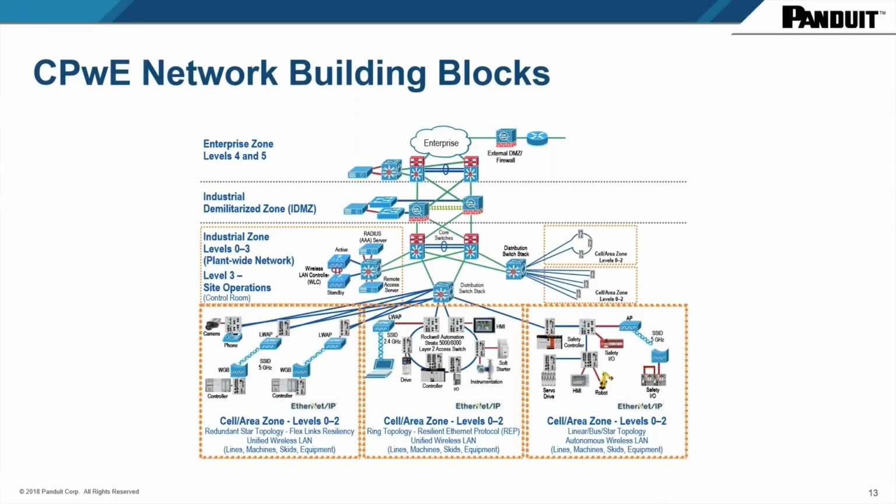As you go up in the architecture, you encounter what we call a DMZ space, and this is the demilitarized zone. This is where we find firewalls and so forth to separate the networks of an industrial network and an enterprise network. And why do we use firewalls? We use firewalls to protect the factory systems from attacks outside the firewalls. Also, we tend to manage traffic between the enterprise world and the factory world. They're two different worlds. On the factory system, the communication is real time.